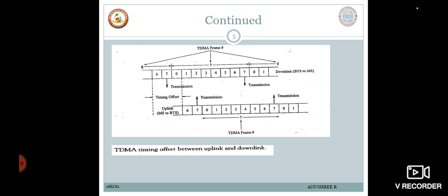Time slots have a duration of 3/5200 seconds, or approximately 577 microseconds, whereas the typical transmitted burst is approximately 546 microseconds. The bit period is 48/13 microseconds, or approximately 3.69 microseconds.